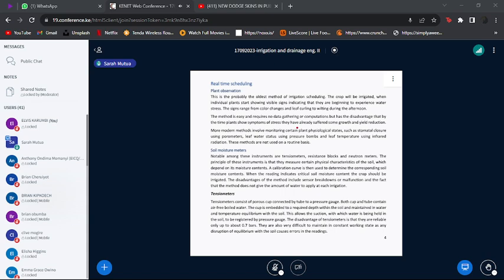And then again, for example, if you see your leaves are curling, for example, maize leaves start to turn like needles, most of the time at that point the moisture content is already below the critical moisture content. So we have nowadays more methods of doing this scheduling, and under this category we have what we call real-time scheduling.